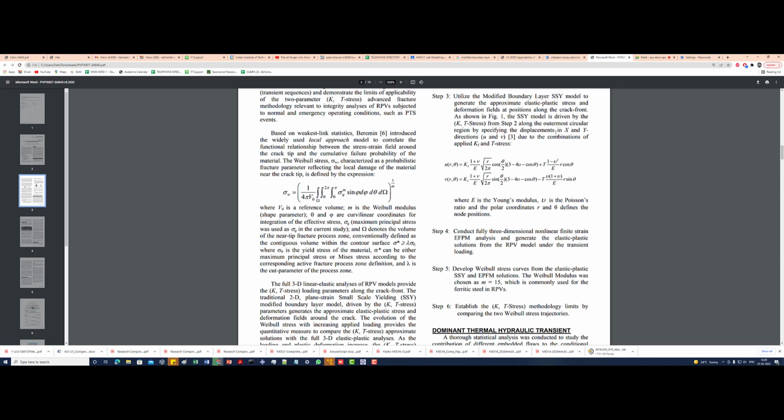So u1, u2, and then you take another point and there you define u1 and u2, and you take different points, and on that you keep on defining u1 and u2. Once you define and apply that, it's all good, and then you can model it, and then you can find out what happens to the stresses and strains in the plastic zone, which is not falling inside the process zone.